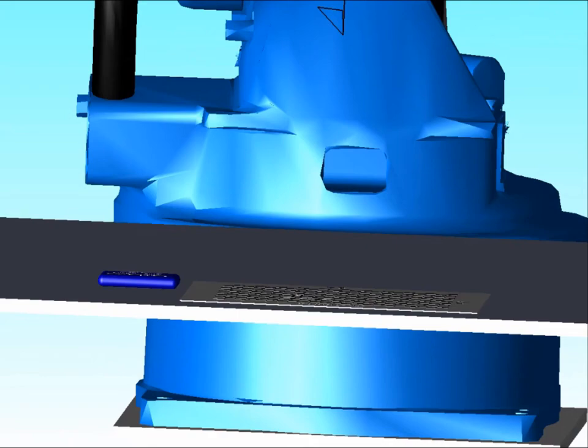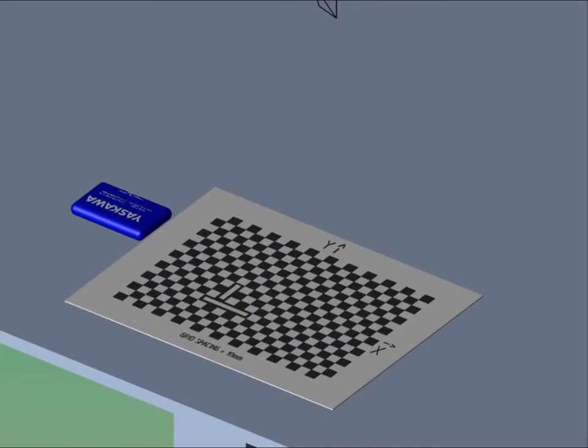Please note that when setting up a fixed camera, the calibration grid should be at the correct work distance, which means that the calibration grid should be at the same height as the workpiece feature you're training in your vision job. In our case, I'm training the Cognex camera to find the Yaskawa logo on top of my workpiece, so the grid calibration should be propped up to the same height as the Yaskawa logo.